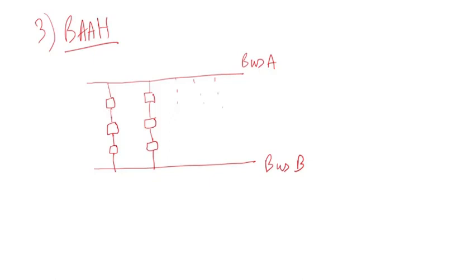So you can see you can only connect 2 terminals on each leg of the breaker and a half. Here are 2 lines, and since I have 4, here's another line, and here's a 4th line. Those are the 4 lines. This is what I call a leg. You have 3 breakers, and you can connect 2 things: 2 lines, or 2 transformers, capacitor banks, or shunt reactors, whatever.